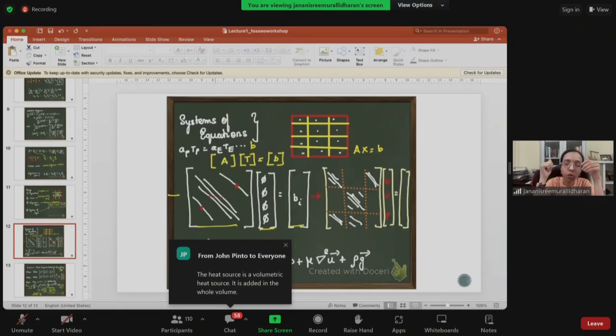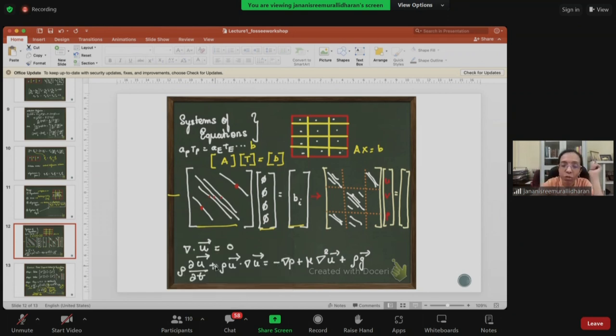So when you have U, V, W, and pressure, you need 4 equations to be able to solve it. You have 3 equations for the different components of the velocity, but for pressure, you don't have an exclusive equation. You just have the equation for velocity again, correct? Like I mentioned earlier on Monday, the SIMPLE algorithm tries to rework this.